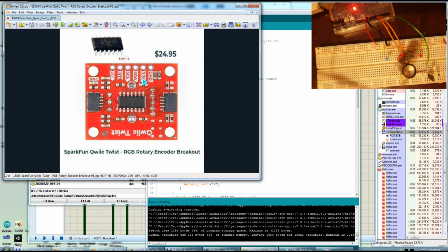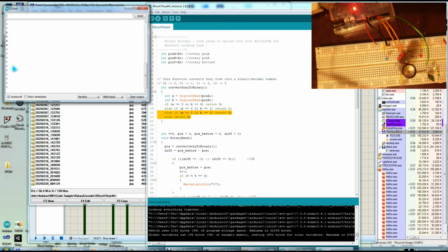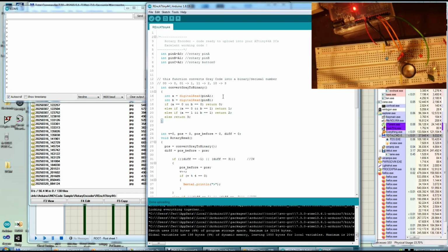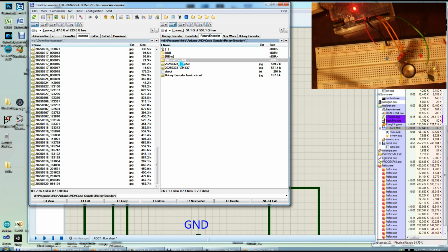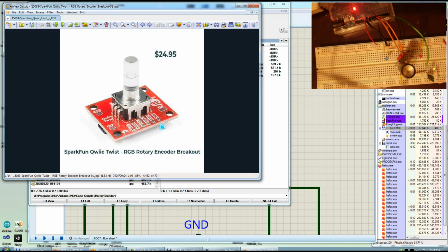Now I'm seeing this little surprise, 3.3. I didn't realize this little detail. So it is a serial communication between this microcontroller and the next Arduino board or the next microcontroller or whatever you are inserting into this connector and trying to pick the data pretty much. And this is my interpretation of how this data should look. Very short characters. You see, it makes this pattern very easy to read in the next code. That's what I did here. But again, this is only prepared to be programmed into a Tiny44 chip through Arduino as ISP, like I showed already. And I will program that microcontroller using this modality. And after that, I will make the actual board with this rotary encoder and with a sturdier board, not on cardboard.